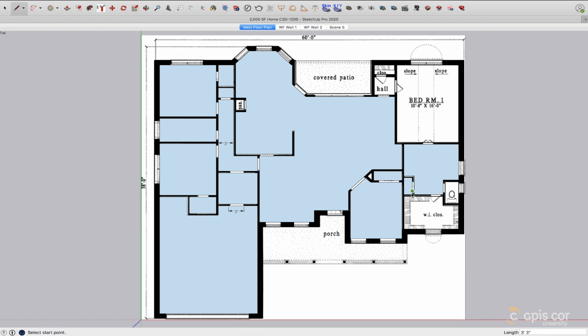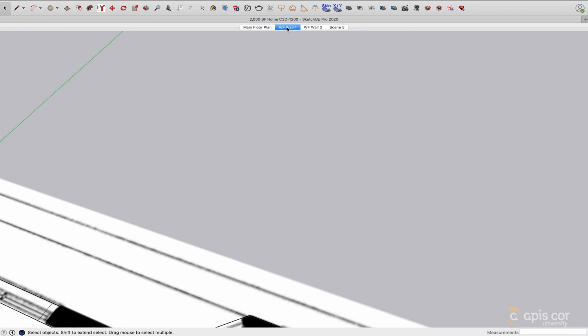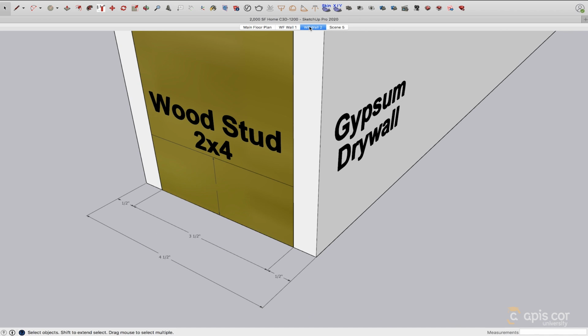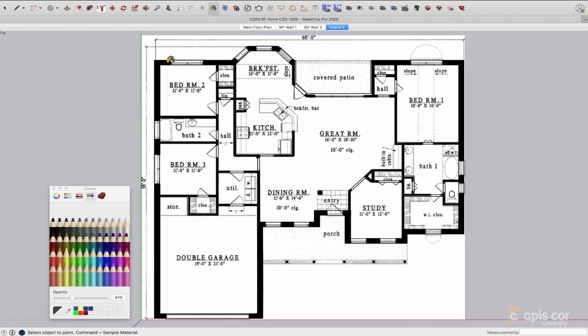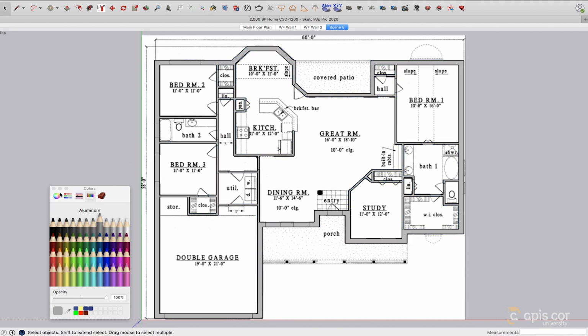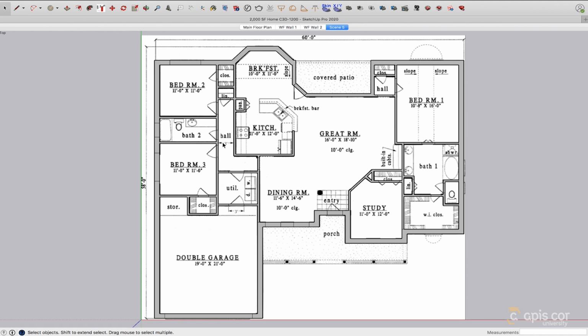These interior walls are 4.5 inches thick, and we know this because interior wood-framed walls are constructed using 2x4 studs and gypsum drywall. Contrary to what the name suggests, the true dimensions of 2x4 wood studs are actually 1.5 inches by 3.5 inches. Assuming half-inch thick gypsum drywall is used on both sides of the wood studs, we're left with 4.5 inches of total wall thickness. However, we are 3D printing this house, so we want to start by converting these interior 4.5-inch walls into either 8-inch printed block walls or 6-inch hollow printed walls.